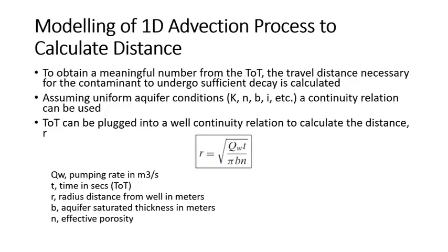Now from there you can obtain how much time you need for your contaminant to reach your safe concentration levels. So you now have your time of travel, and to make it practical and enforceable as a wellhead protection area, all we have to do now is calculate the distance that is involved to allow that time of travel to occur.